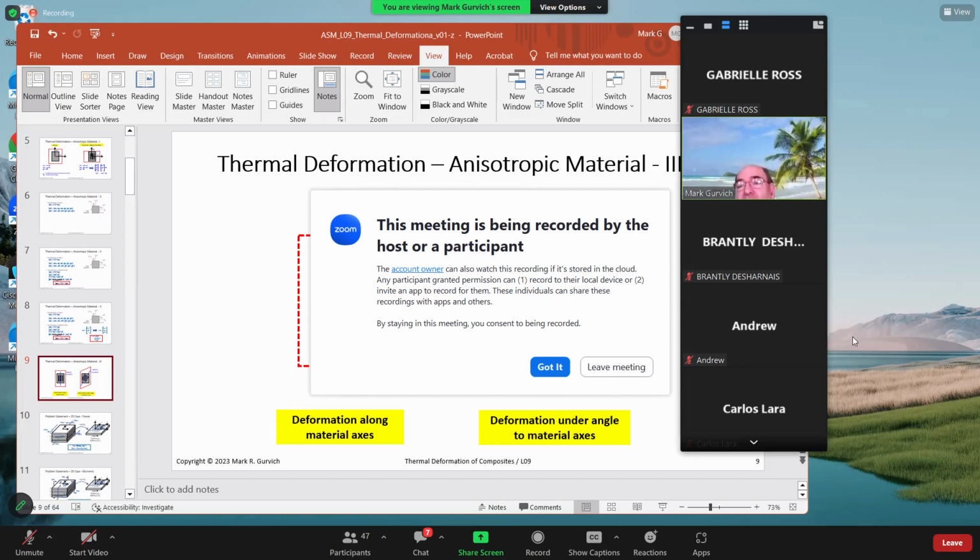I don't know if you pay attention, like with plywood sometimes, upon heating, but usually upon absorption of humidity or moisture, it starts to buckle. Actually, this is the effect, because in plywood you have different layers oriented under different angles, and each tries to shear in a different orientation, and because of that it could influence deformation.